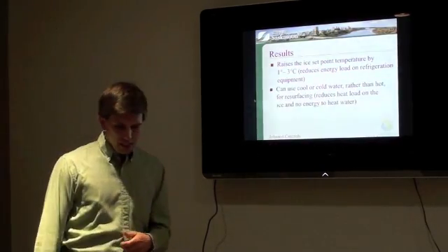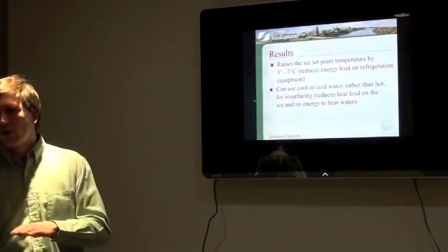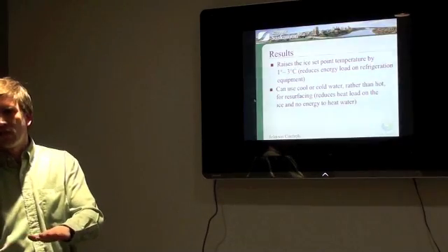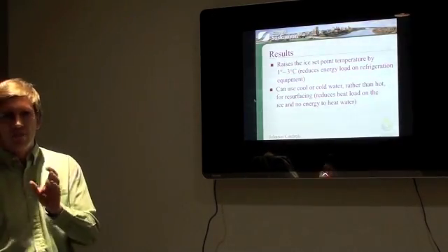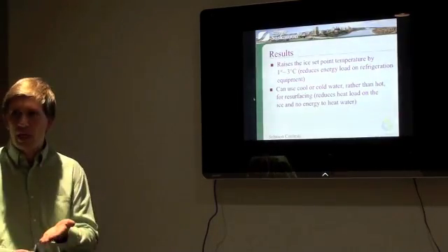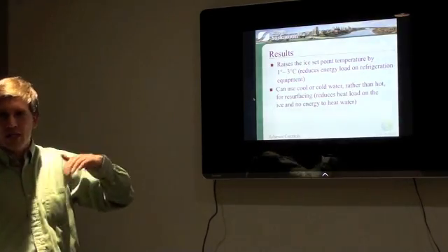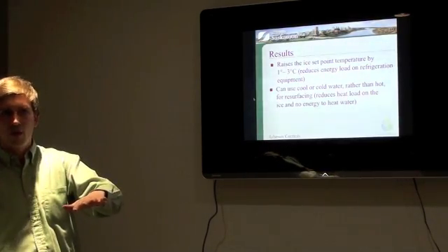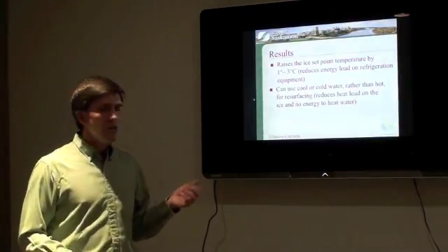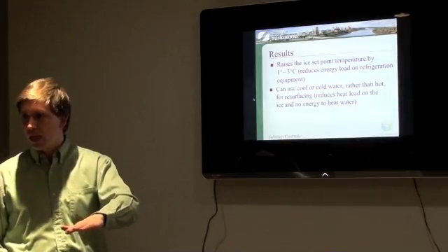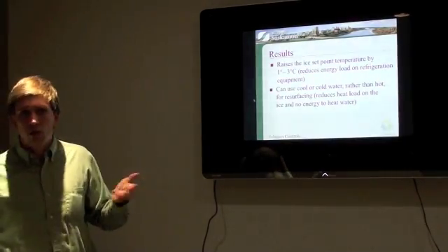Another thing that this bacteria does, because of how it promotes the freezing, is that you can use cold water or cool water when you're cleaning the ice surface with a Zamboni. Normally you need warmer water because it has to melt the cracks in the ice and help it flow together. With this, the cold water can seep into the cracks, lay a surface, all freeze at a uniform time, and make a good skating surface again. So you don't need to heat the water. By not putting hot water on the ice sheet, you reduce the cooling load of the equipment again, and you don't have to heat the water. So it's kind of a double savings.